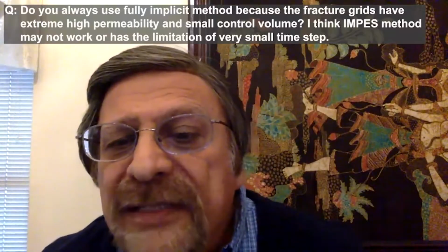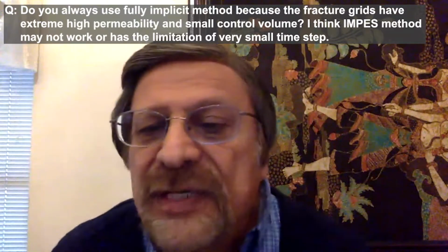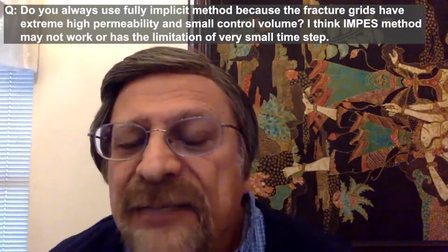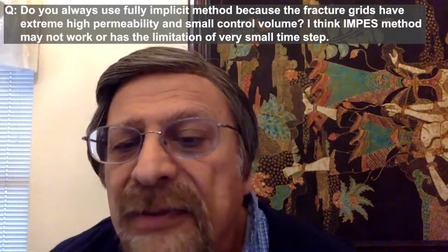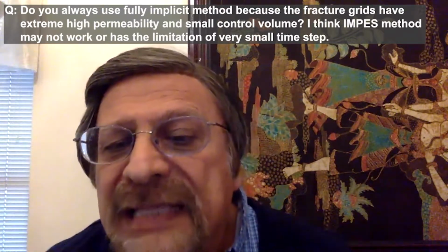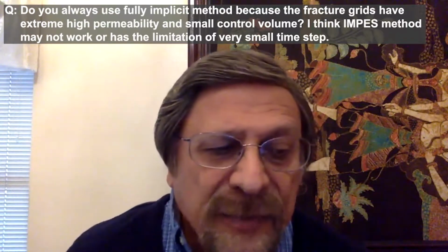Do you always use a fully implicit method because the fracture grid has extremely high permeability and a small control volume? I think the IMPEC method may not work or has the limitation of very small time steps. Well, to be honest, when you're using EDFM, you're looking at conductivity rather than using very, very small grids. So some of those problems are alleviated by using EDFM.